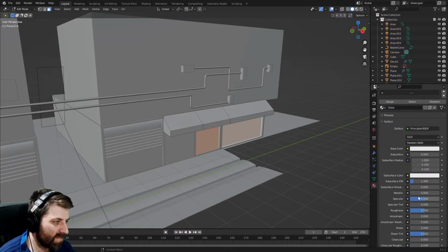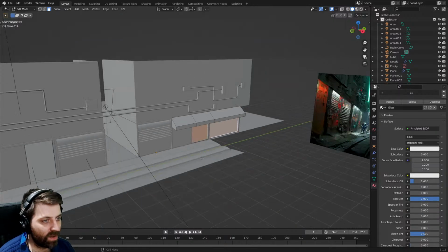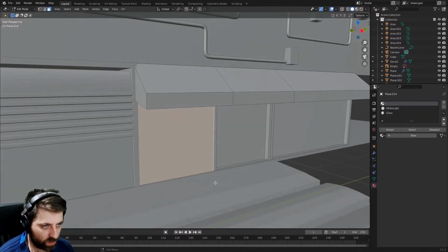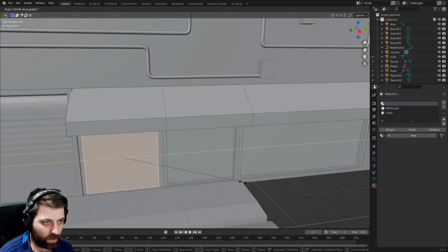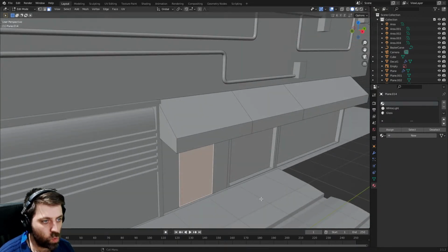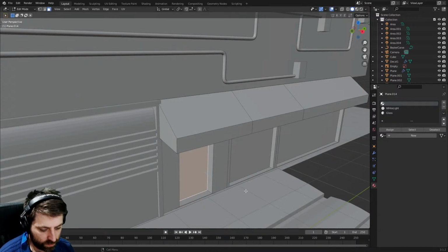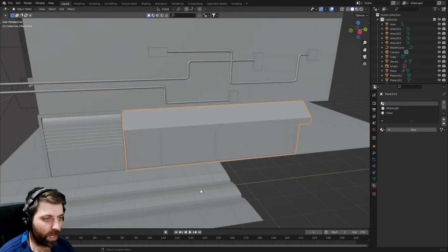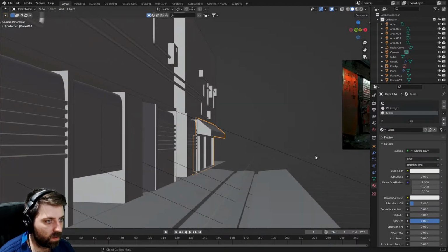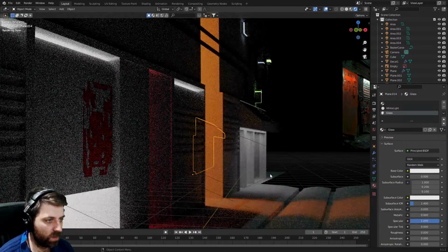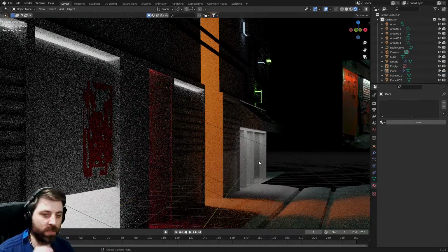Let's make it specularity up, roughness down. I mean, I could probably make an actual glass material, but we will come back to that one. Let's do I to do an inset on here. Scale on the Y. E to extrude. I. E. Let's grab them. Assign. Yeah, we're not really going to be seeing much, but that's fine. And if we come into this view, yeah, sweet. So we're going to work around creating a...